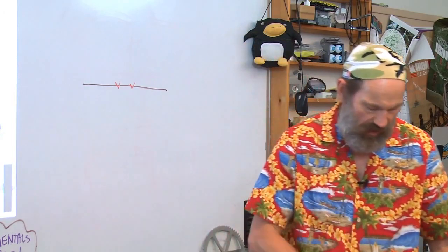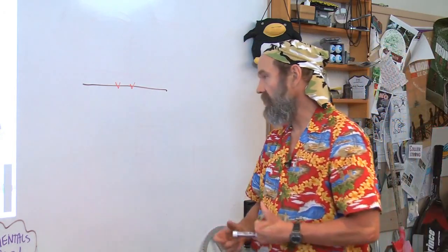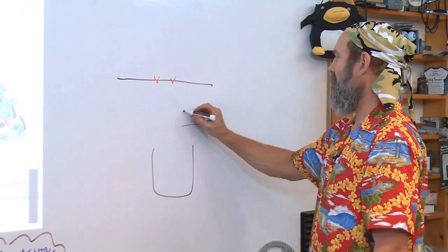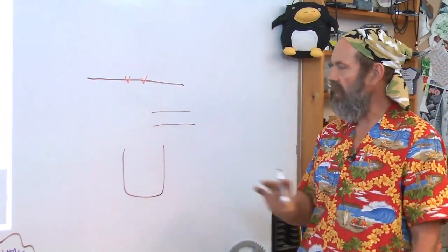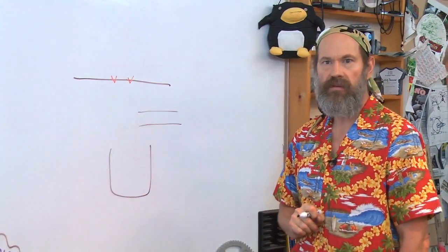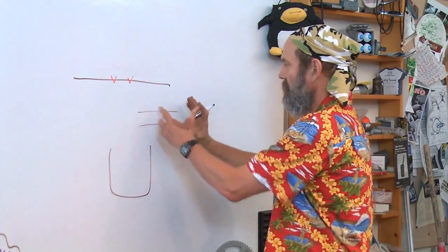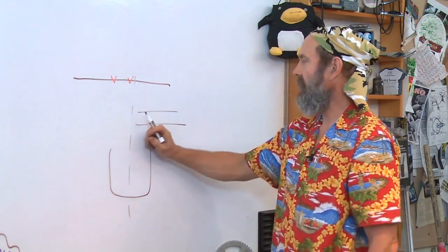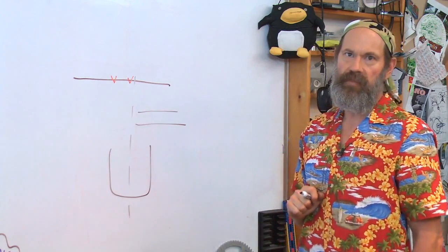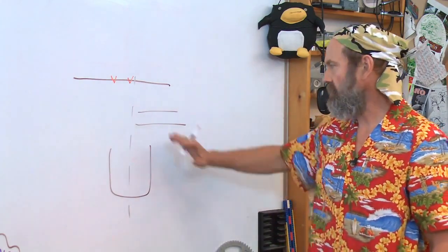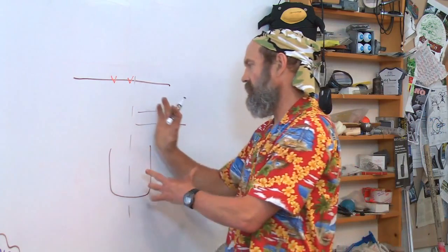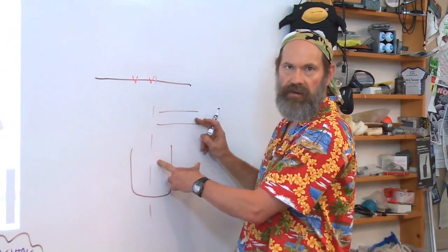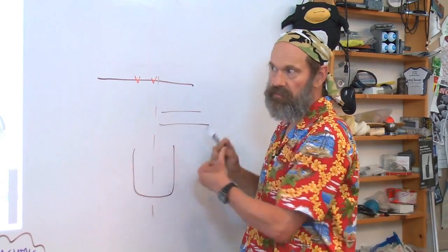So how do automotive wheels work? How do they, with a big fat tire, and here comes the axle, skinny little axle, how do they mount that in a car? Where are the bearings that support the axle versus the center of the wheel, and how do they keep that shaft from being overloaded? Look at a cross-section through a car axle sometimes. See how they move one structure into another to achieve good loading on the bearings without violating St. Venant's principle.